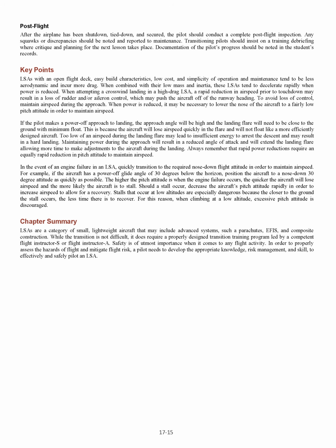The higher the pitch attitude is when the engine failure occurs, the quicker the aircraft will lose airspeed and the more likely the aircraft is to stall. Should a stall occur, decrease the aircraft's pitch attitude rapidly in order to increase airspeed to allow for a recovery. Stalls that occur at low altitudes are especially dangerous because the closer to the ground the stall occurs, the less time there is to recover. For this reason, when climbing at a low altitude, excessive pitch attitude is discouraged.